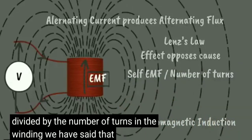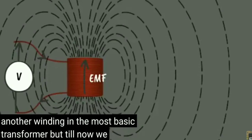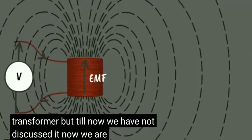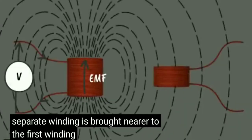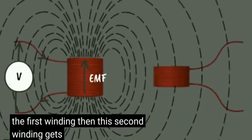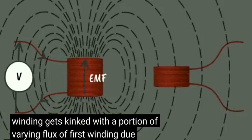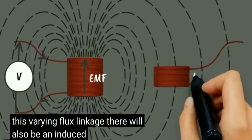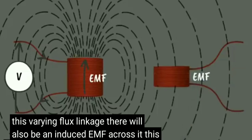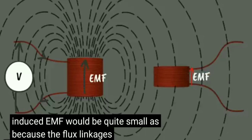We have said that there is another winding in the most basic transformer, but till now we have not discussed it. Now we are coming to the second winding in the transformer. Suppose one separate winding is brought nearer to the first winding, then this second winding gets linked with a portion of the varying flux of the first winding. Due to this varying flux linkage, there will also be an induced EMF across it. This induced EMF would be quite small, because the flux linkage is small.